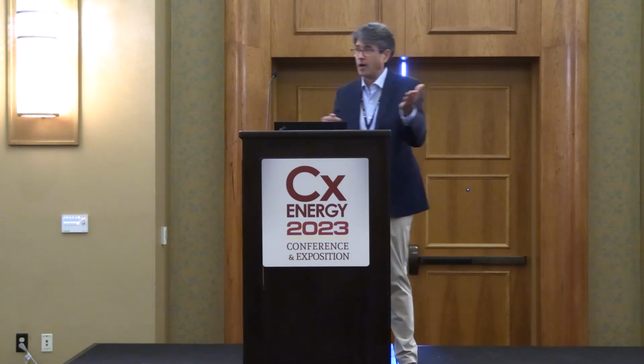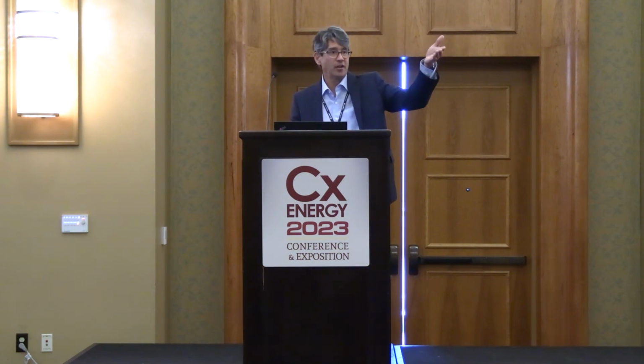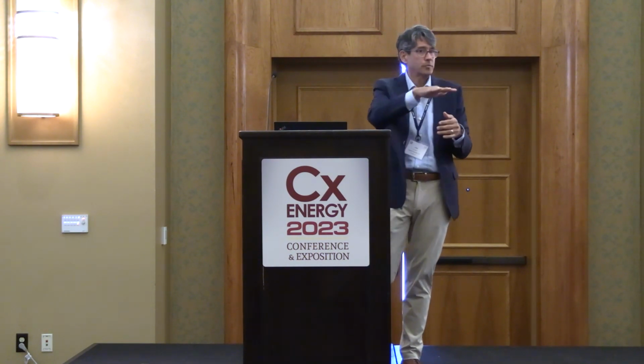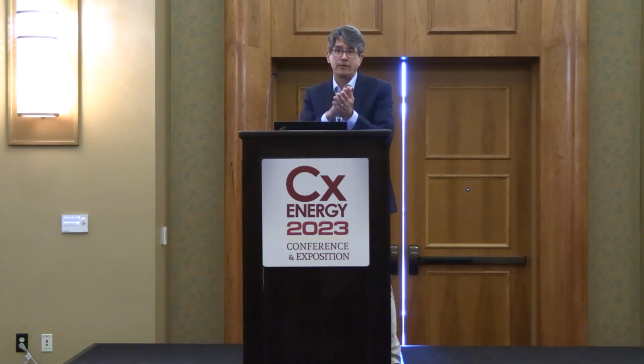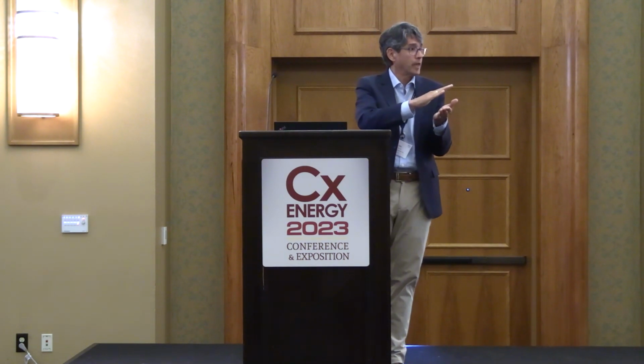It's controlling probably minus 10 to plus 10 or some range in that side. So you go back to prove up, and now all of a sudden your numbers are below design number, they're below the 0%, so hey, you need to rebalance it. Well, how's the control system controlling? Better yet, plus or minus 5. We'll balance to the plus or minus 5 tolerance, but can the control system control to that level?